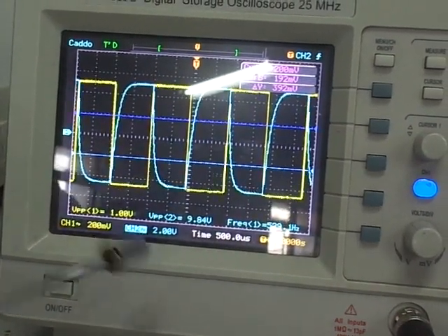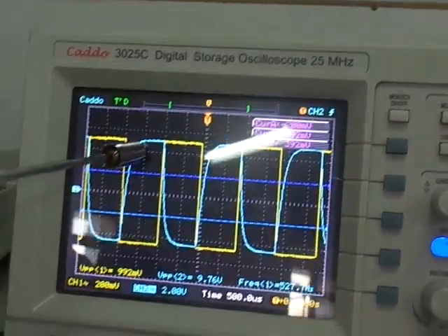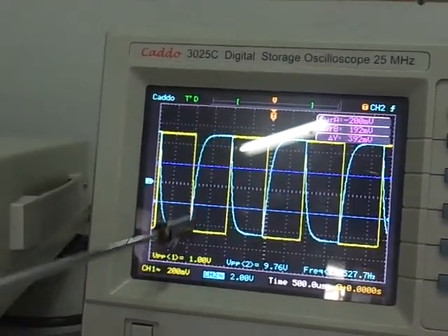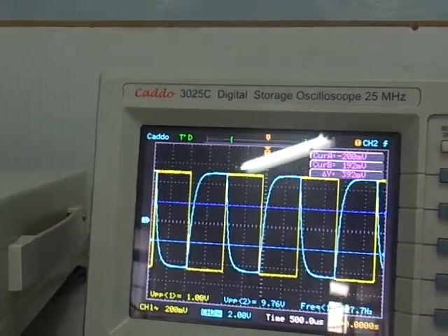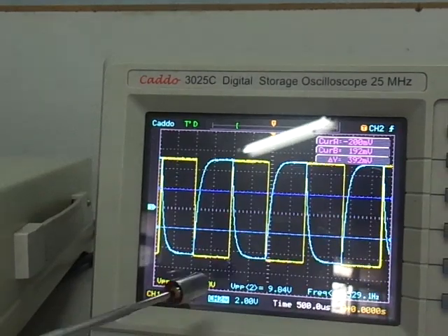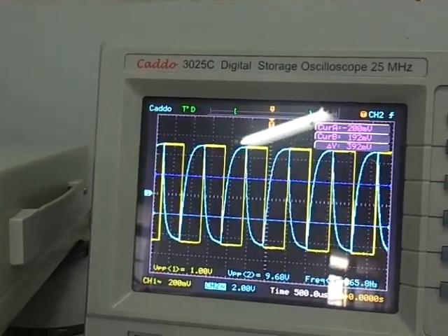Now if you see the waveform, first thing is amplitude goes on decreasing for the output signal, as well as the shape of waveform goes on changing, means it is tending towards a triangular wave now. Means our circuit is reaching an integration mode. This result we are getting at 500 Hz. If we take the next measurement at 1 kHz,